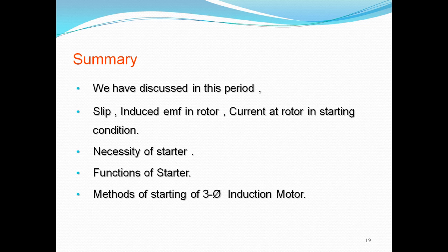At the time of starting, the handle of the starting resistance is at the start position, so that maximum resistance is added in each phase of the rotor circuit.